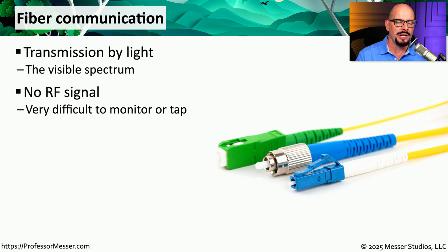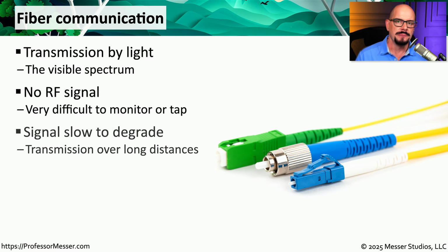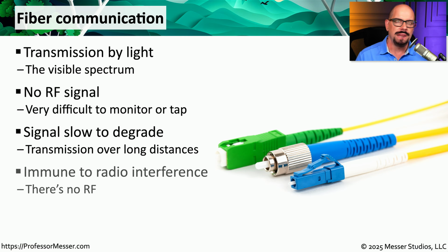You do need specialized equipment if you're planning to use a fiber optic network. But unlike copper signals, which tend to degrade over a short period, in some cases you can extend fiber optics many kilometers without needing to regenerate that signal. And if you're working in an environment with a lot of industrial equipment or you're having to deal with a lot of interference, you could install fiber optic connections and not worry about any of those radio frequency interference sources.